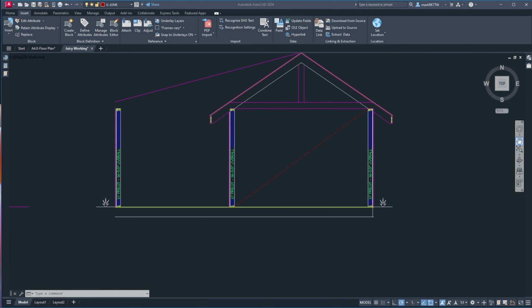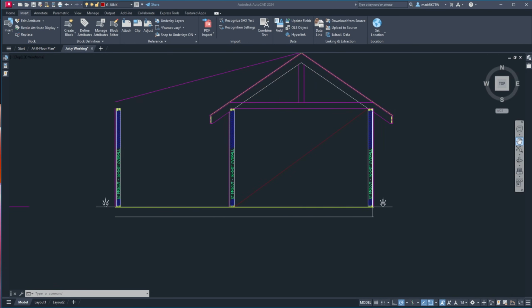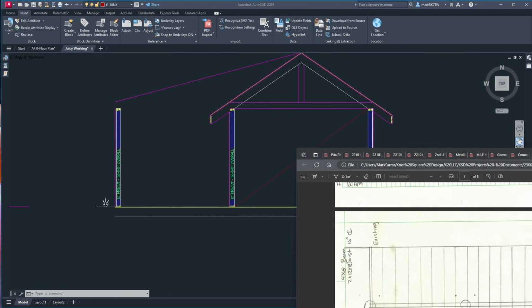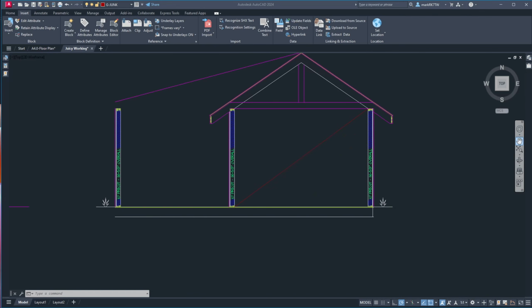So what code's going to tell us is that any wood is going to have to be 8 inches clear underneath in here. It's not like your siding that only needs 6 inches clear to untreated wood. So your sill plate is typically treated, so that can be within that 6 inches.